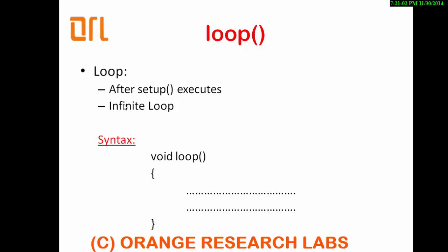When you go for a normal system, when you go for a simple C program, your C program will be called for only one time. But when you go for an embedded system, your program should iterate for an infinite number of times because an embedded system is nothing but integration of both hardware and software. Until the power supply goes off, your program should be iterated.